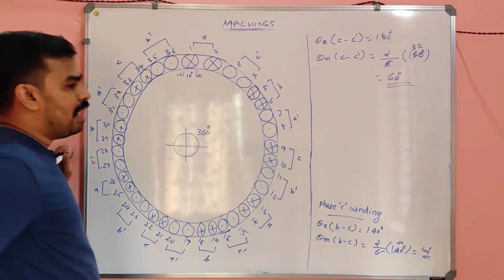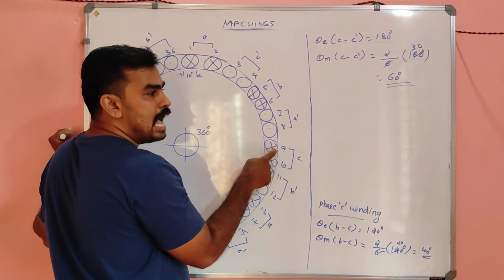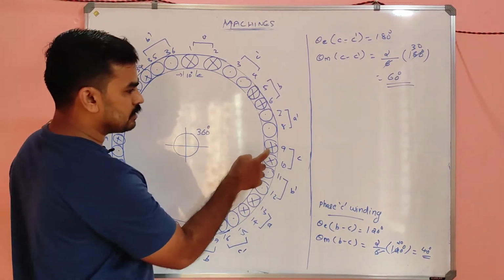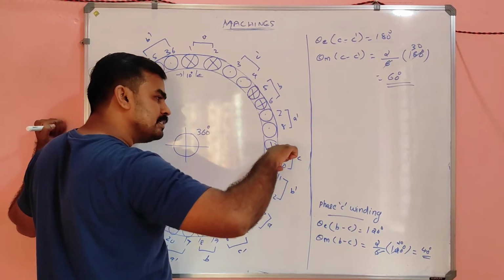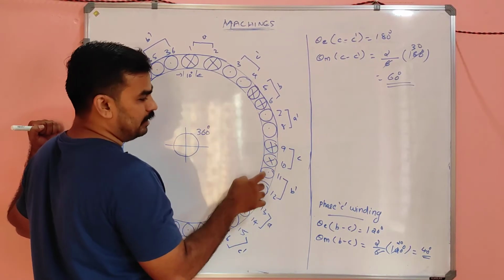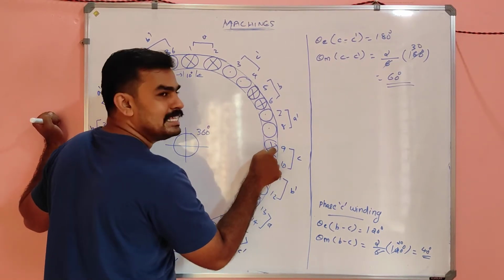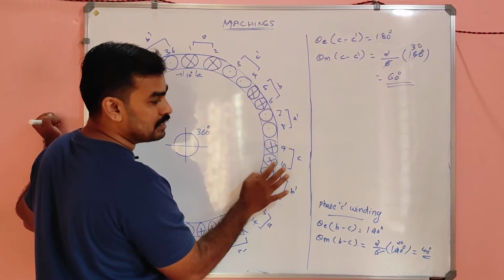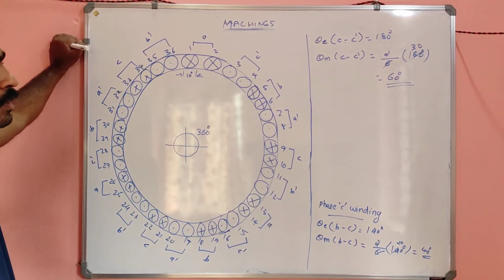That means after we wind the starting end of phase C, after 60 degree only C dash will be taken outside. That means this is the into coil, and this is the outward coil. Okay, so slot number 9 is the into coil. No, slot number 10 was the into coil, correct?